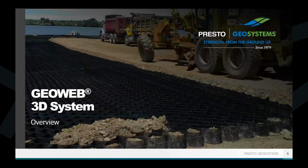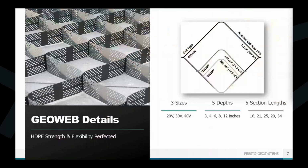Here we go. So let's cover a little bit about the general information about GEOWEB geocells, so we're all on the same page. The GEOWEB system has 2 main characteristics, and the first one is going to be the cell, or basically the container size, the diameter, and the depth. The cells do come in 3 diameters, basically a small, medium, and large. And then the cell heights are going to range between 3 and 12 inches.